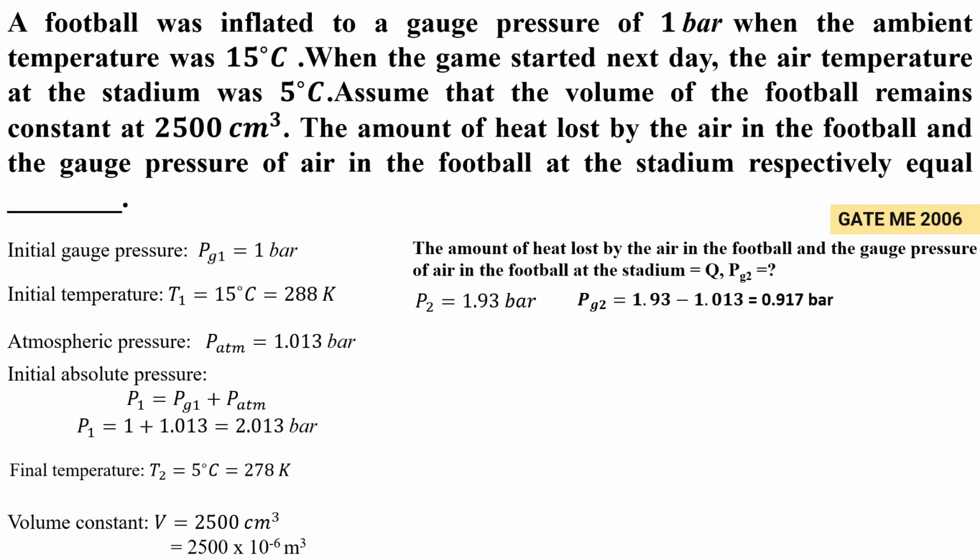So okay, we determined the final gauge pressure. Then I have to determine the heat loss Q. We know Q equals m Cv dT. The m value we don't know, so in this regard I have to use the PV = mRT equation.